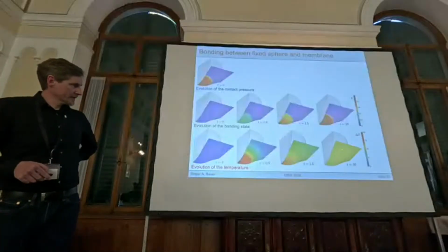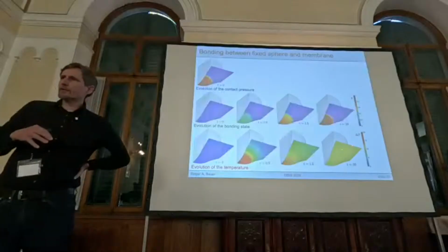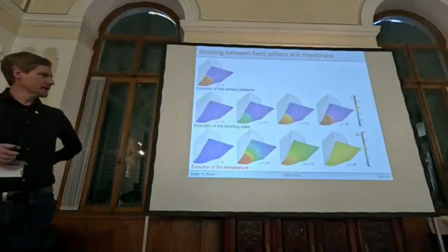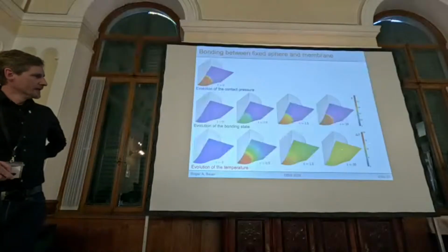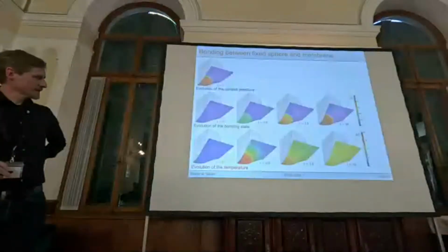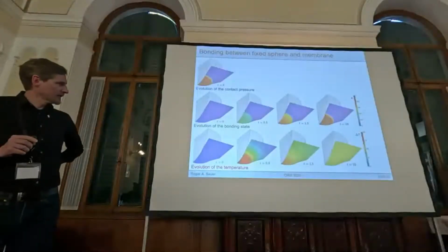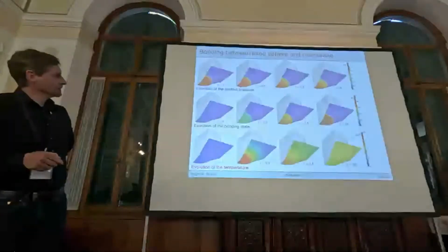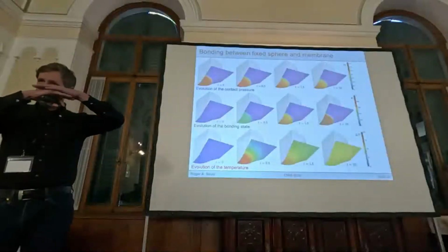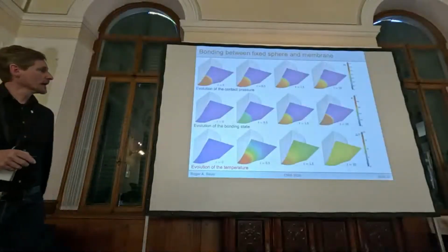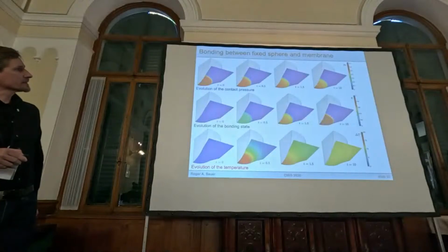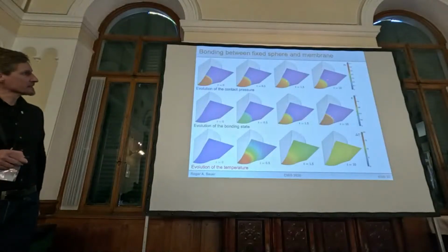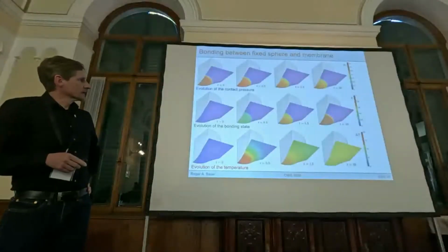One can now check that the analytical solution I've shown earlier is able to estimate correctly the temperature increase, and that is the case. So one can confirm that the energy is not lost. And then lastly, because of thermal expansion, because of the increase in temperature, the pressure will go down. Now the sphere is fixed, so since the sheet expands in size, the contact pressure will decrease.